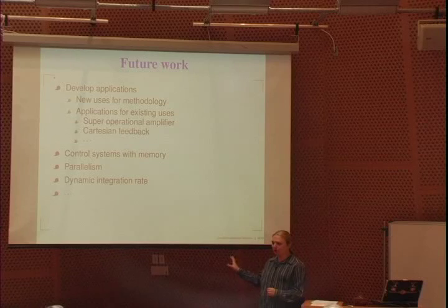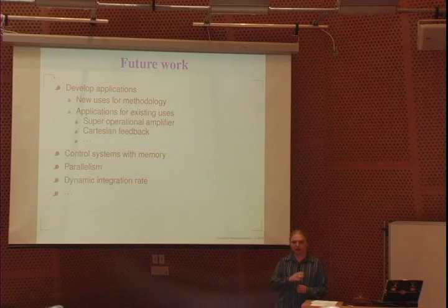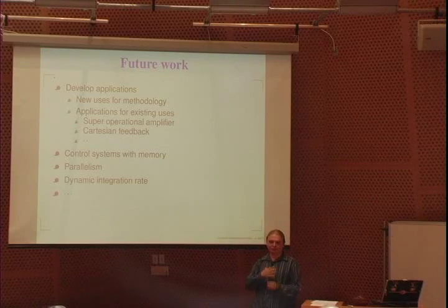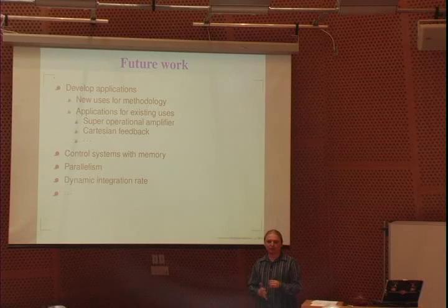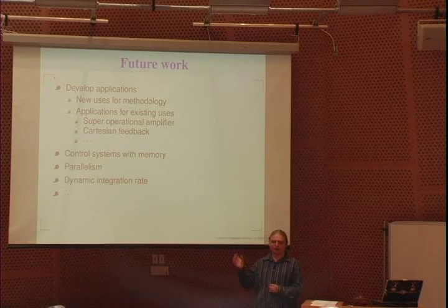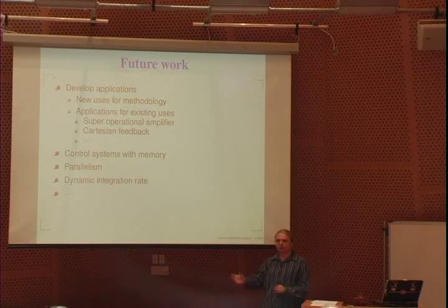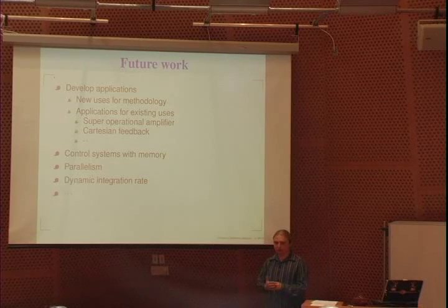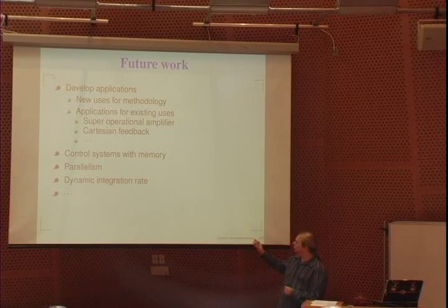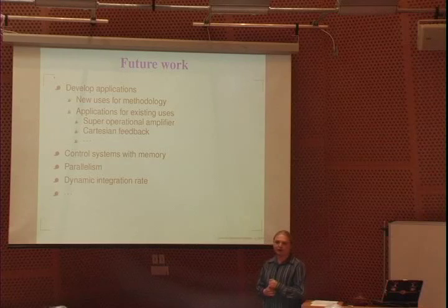and then you play back those inputs from a digital memory. This is very useful in RF because, as I said, there's a delay in the system, there's a modulator and a demodulator, and in the RF stage, if you have a very linear gain stage, it has very bad efficiency. If you have a very nonlinear one, you can make it high efficiency, but it's hard to do both at the same time. So this could potentially be used as a modeling technique there.